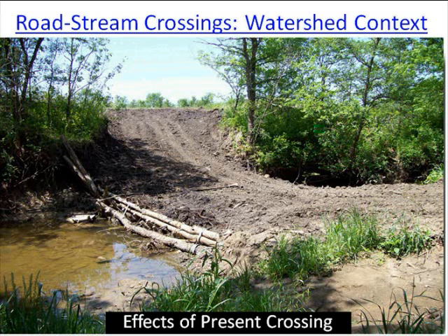In addition to knowing where you are within the watershed and its transport or response potential, it's also important to identify conditions that will affect channel and floodplain processes at your crossing site. For example, landslides can introduce huge sediment and debris loads into a channel. Active head cuts adjacent to your crossing site can migrate and endanger longevity. Analyzing the flow regime will help you characterize flow extremes that can affect passage and crossing dynamics.